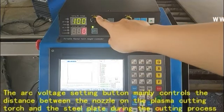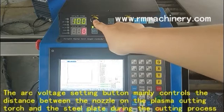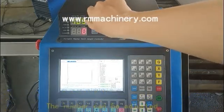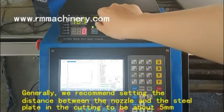Arc voltage setting button mainly controls the distance between the nozzle on the plasma cutting torch and the steel plate during the cutting process. The number can be adjusted. Generally, we recommend setting the distance between the nozzle and the steel plate in the cutting to be about 5 mm.